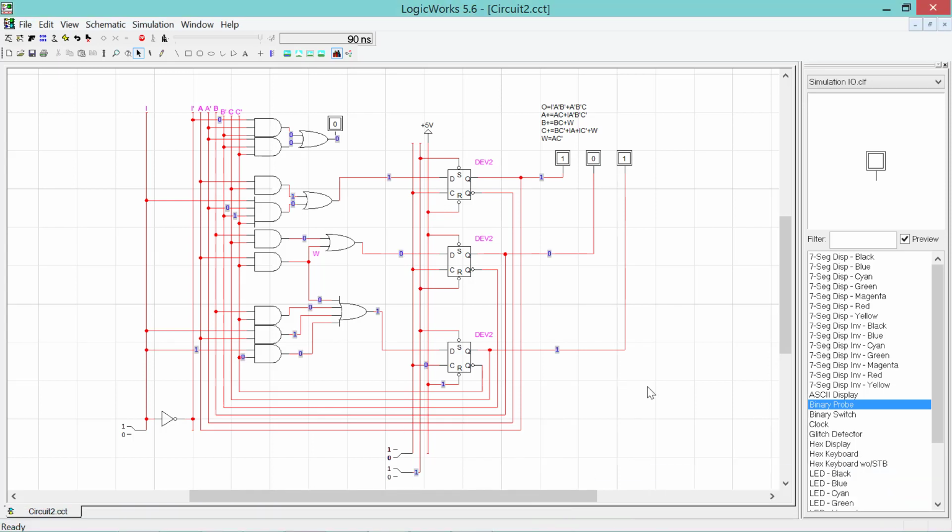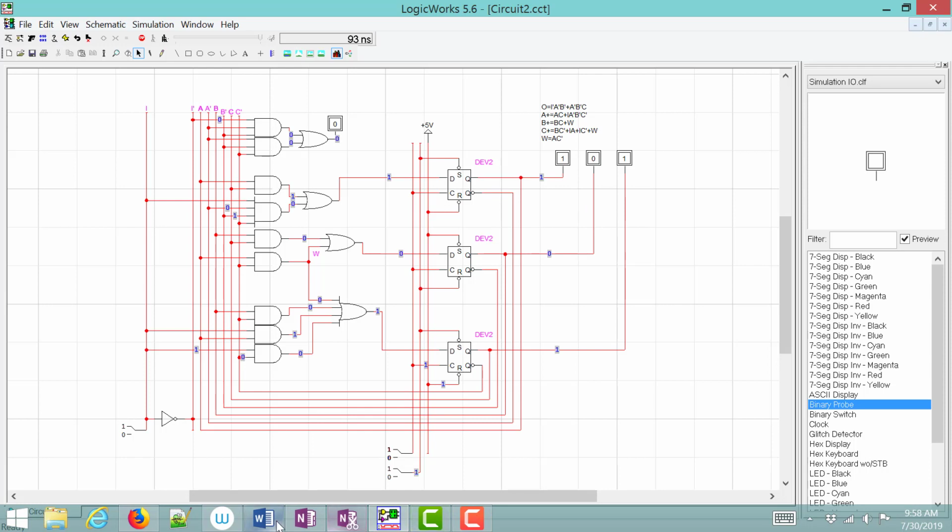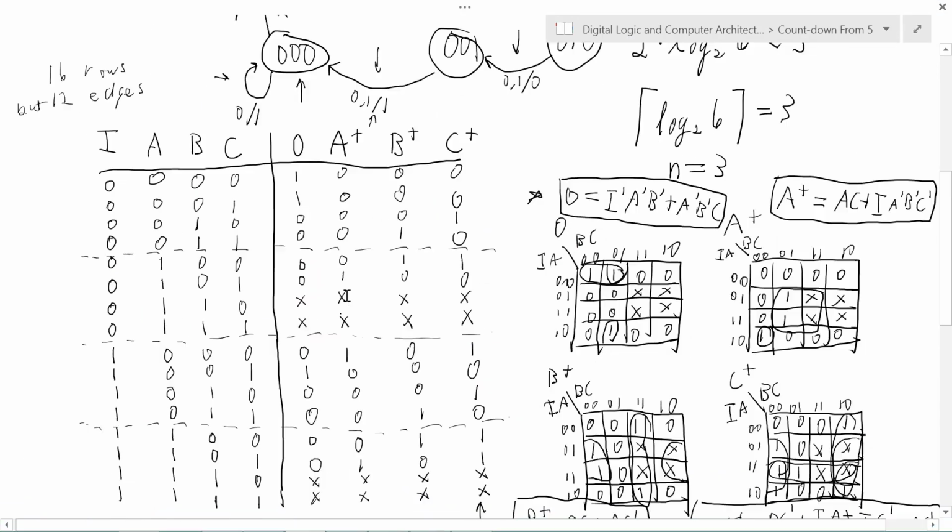We now see an error here. What is interesting is we are setting the reset signal, but this should only activate from state 0. For some reason, we are staying in state 5. Is this proper behavior? Let us look at the state machine.